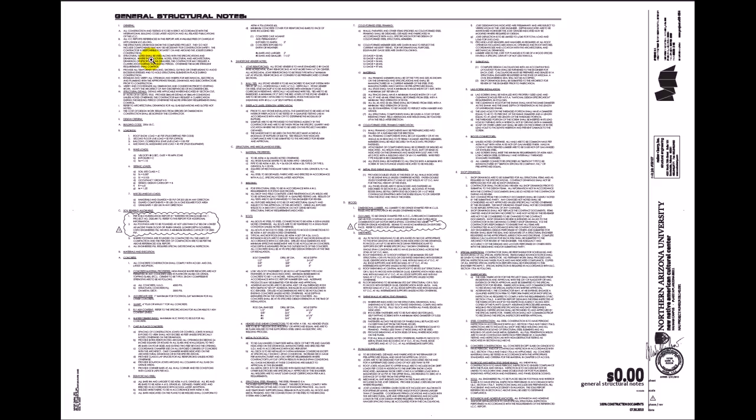So I'm going to go back to the beginning, the general structural notes. And the general structural notes really give the detail about this type of building. There are specifications that will tell exactly how to build each part. However, the structural notes are different than most other trades where the specs take precedence. In structural drawings, typically it's the structural notes that take precedence over the specification. So let's jump in here, and by reading through the general notes, by skimming through them, we can get a good feel for a lot of the assumptions of this building and the materials.